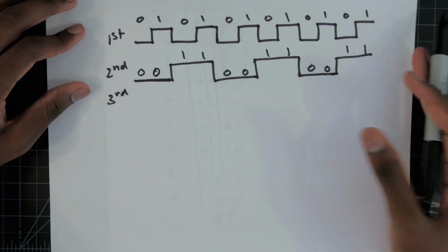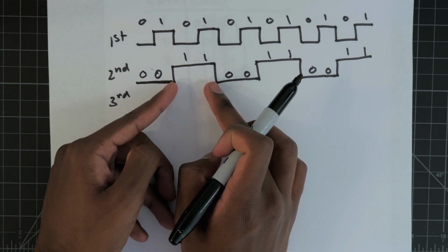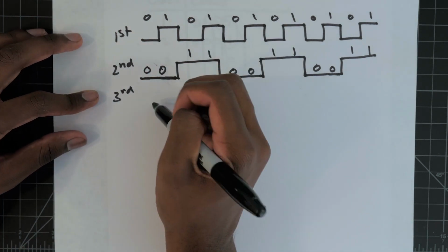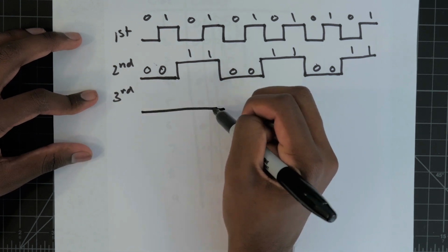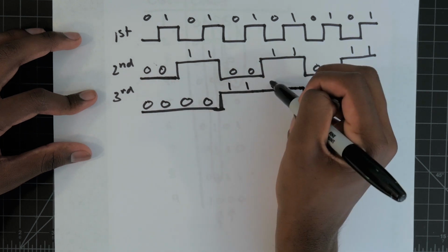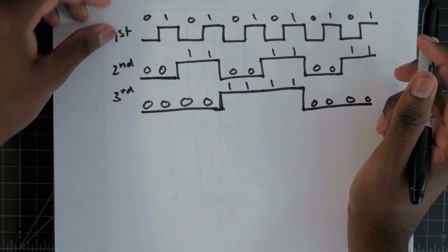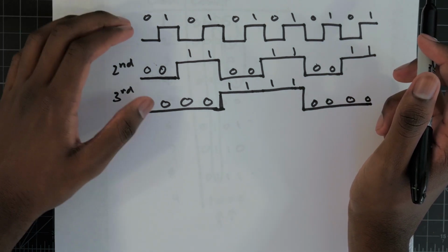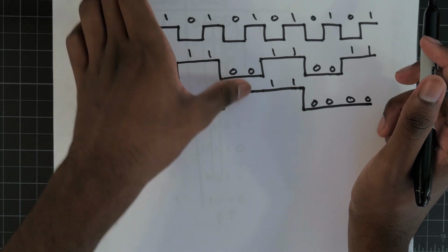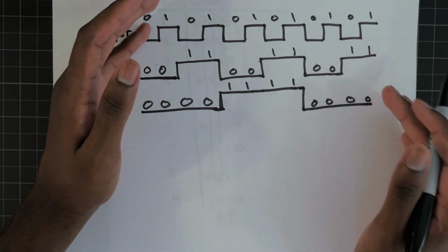So we're counting along. But you can also see that looking at the clock signals, treating each of these digits like clocks, the period length for this second digit is exactly twice as long as the period length for the first digit. Likewise, if we look at the third digit, we can see for every 2 changes in the second, we're going to get a single change in the third digit. So we get 0, 0, 0, 0, 1, 1, 1, 1, 0, 0, 0, 0. Now we can take a look at the counting. We start at 0, 0, 0, then 0, 0, 1, 0, 1, 0, 0, 1, 1, 1, 0, 0, 1, 0, 1, 1, 1, 0, 1, 1, 1, and so on and so forth, right?